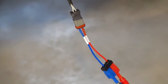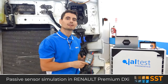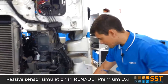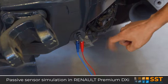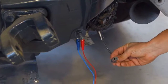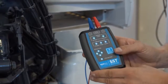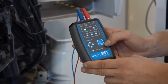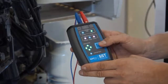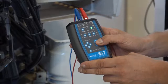After checking the correct status of the sensor, we want to send signals of an inductive sensor to the control unit from Jaltest SST. To do this, we change the connections to the control unit and not to the sensor. We turn the device on, make 4 short keystrokes and confirm the mode by pressing for 2 seconds.